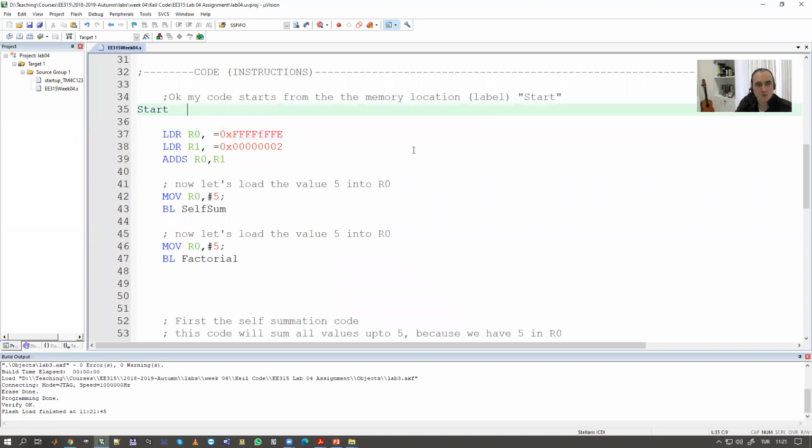Recording, right? Okay. So I've got everything ready. What I'm going to do is debug my code. Debugging means I'm not going to let the clock run. I'm going to just tell the clock, okay, get to the next program counter, because debugging is actually freezing the program counter so that you can analyze your program. So where to stop? This is my first line of code, right? I'm just clicking here. I see a red circle button, which means when the code starts to run, it will stop there and wait for my instructions to continue.